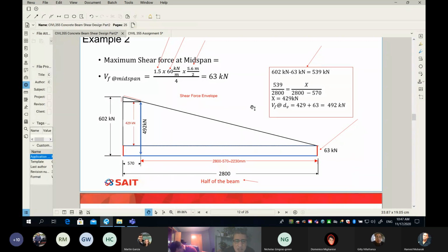It means there is not a single situation where the shear force can be more than what you see. Whatever the live load goes in the middle, goes to the left, goes to the right, jump, run in the air, doesn't matter. Your shear force cannot be more than what you see on the screen, and that's what you should look for, an envelope, not a diagram.